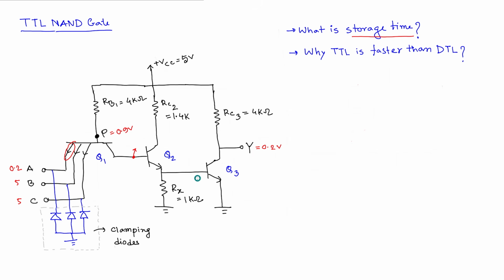Still we can say the voltage we are getting is 0.8, and also 0.8. As a result, the voltage here is 1.6 volt, right? And 1.6 volt is obviously higher than the voltage we have at base, so this particular junction is currently in reverse biased mode.